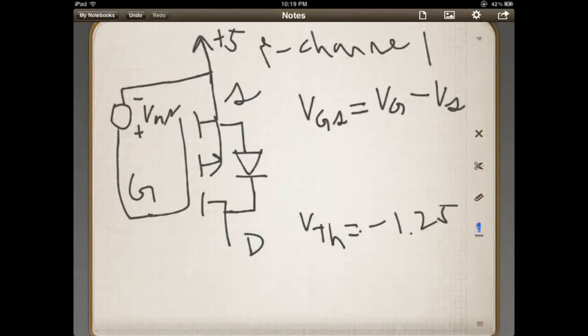So now that goes to show you that if you put 5 volts on this, remember a P channel is the reverse, and when you put 5 volts on it, it turns it off. Okay, so if I put 5 volts on it, what's going to happen?